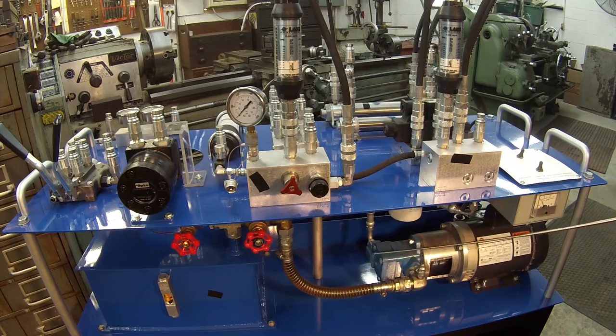Alright, the next thing is a hydraulic pump, and you'll notice that the pump is mounted below the oil level in the tank right here, and that's always the best way to do it because oil has weight to it and it keeps the pump primed whenever the pump is below the oil level, so that's always the preferred method on the pump.